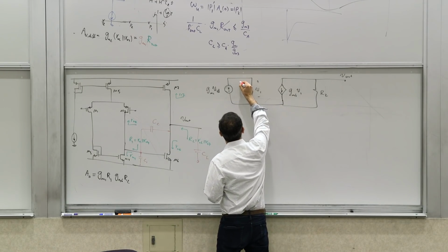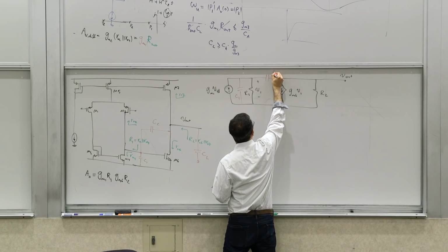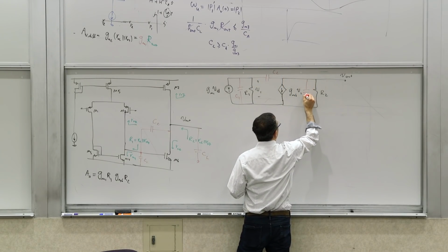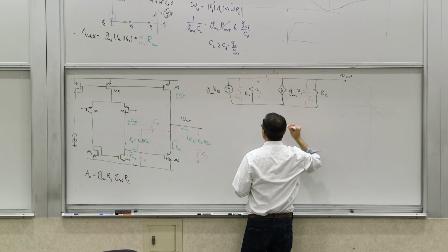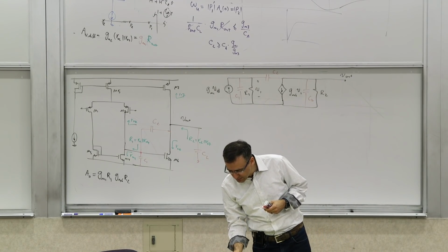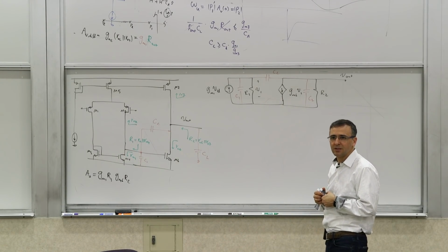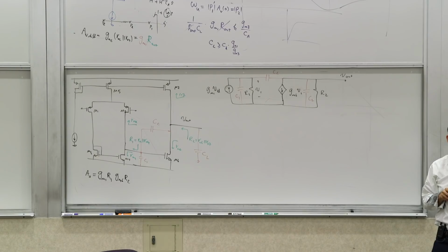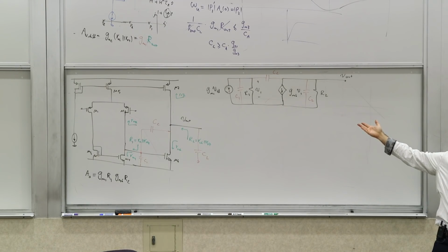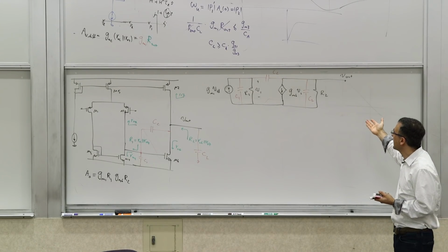If you look at this model, you have this C1 that was sitting there. You're introducing this CC, and then you have an extra capacitor CL, the load capacitor. So what is the transfer function of this thing? This is something we've looked at before. When we analyzed the common emitter or common source, it's exactly the same arrangement. This looks like a common source with R1 and R2 being there.